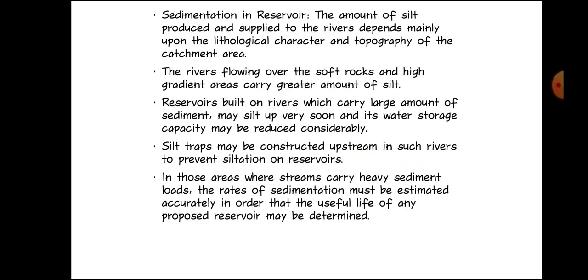Sedimentation in reservoir. The amount of silt produced and supplied to a river depends mainly upon the lithological character and topography of the catchment area. Rivers flowing over soft rocks and high gradient areas carry a greater amount of silt.